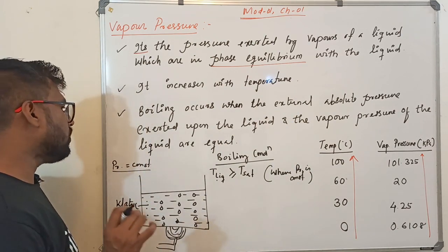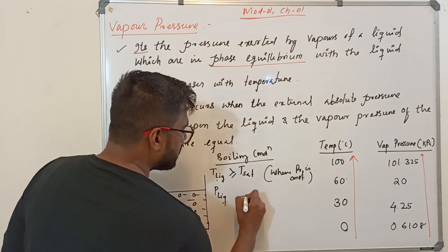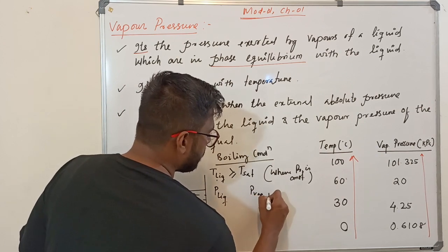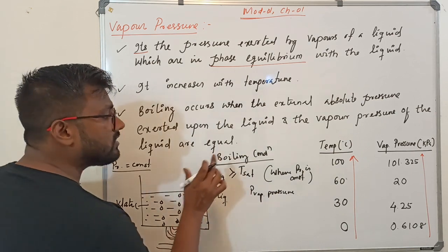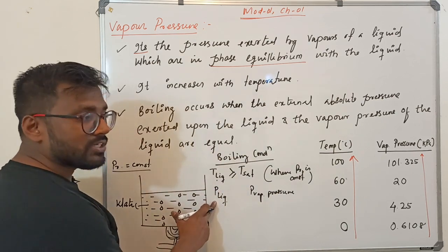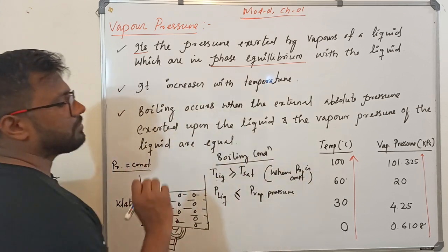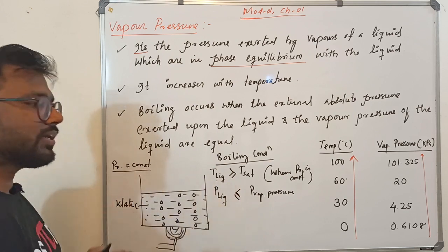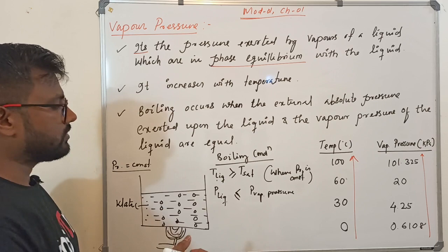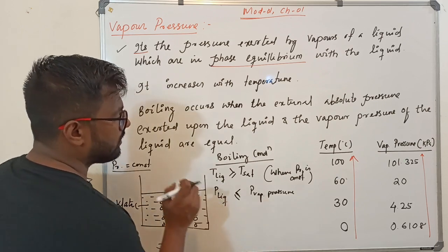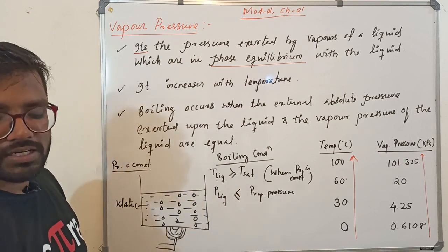So, are you trying to say that the pressure of the liquid has some relation with its vapor pressure? Yes, I want to tell that. The second condition of boiling is when the liquid pressure falls below the vapor pressure of the liquid. At a certain pressure the liquid starts boiling. So if your liquid pressure falls below the vapor pressure, then also your liquid will start boiling.